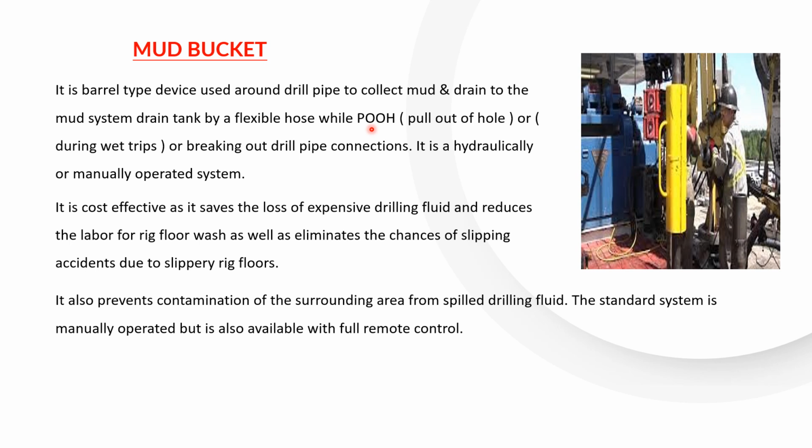It should not fall on the rig floor, so we use the mud bucket. When we use the mud bucket or mud saver, it does not allow the drilling mud to fall on the rig floor, and through the hose it goes to the drain tank. And it will be utilized for the next operation.